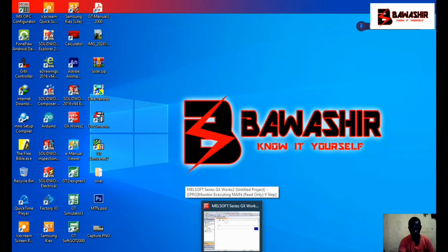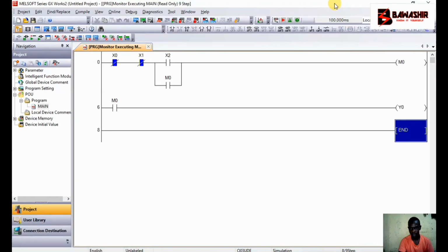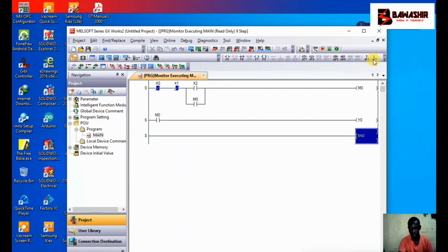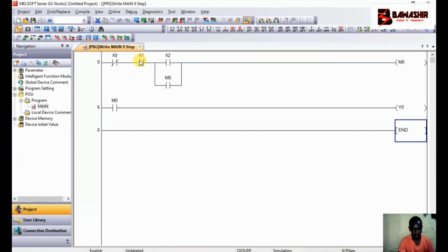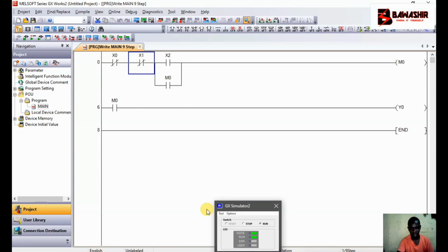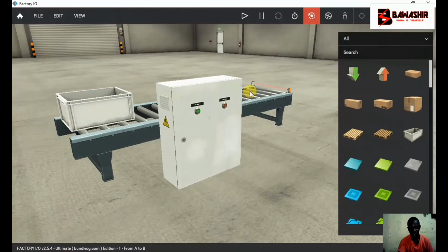Allow me to make some change, and please, if we are doing PLC programming, we should always put in configuration the type of contacts you are going to connect physically and the programming here. What do I mean? Let me first put this in the right mode. So here our stop push button, it is normally closed. This one here is normally closed.